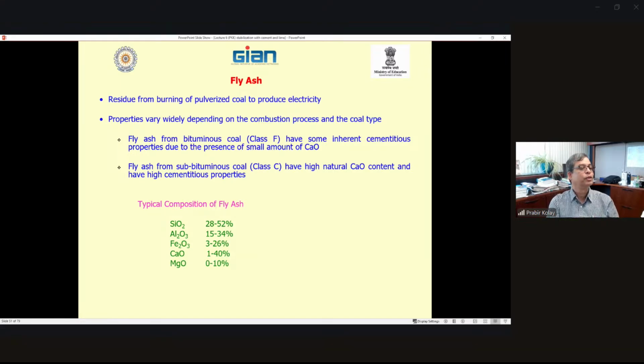And it will corrode the reinforcement. So we don't want that. So again, there is a concrete thing. So people are using it, but the reaction mechanism is the same whether you use it in cement, in soil, or cement in concrete. They're the same alkali silica reaction: calcium silicate hydrate, calcium aluminate hydrate.